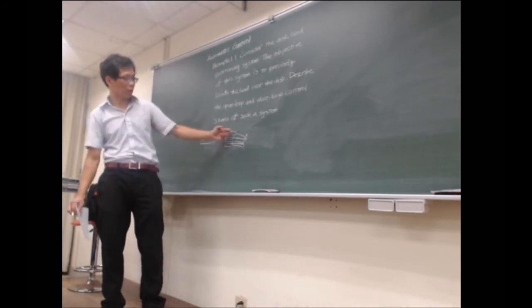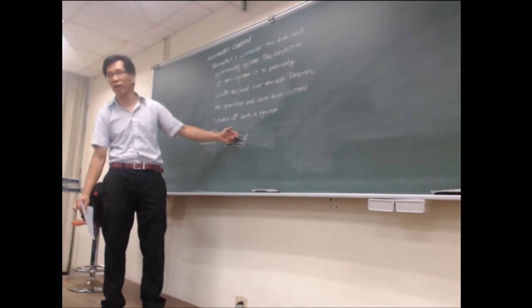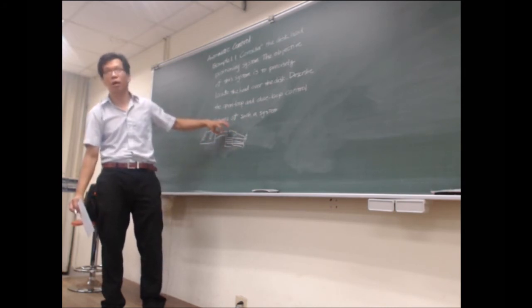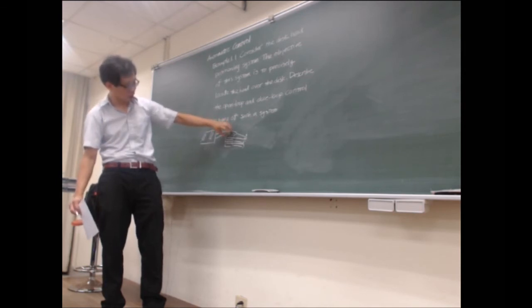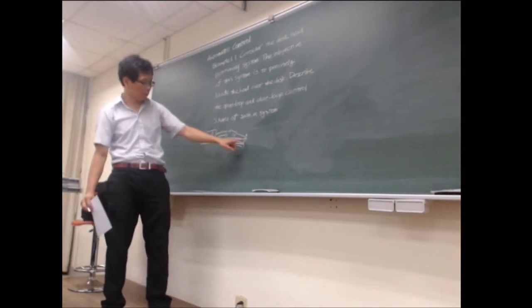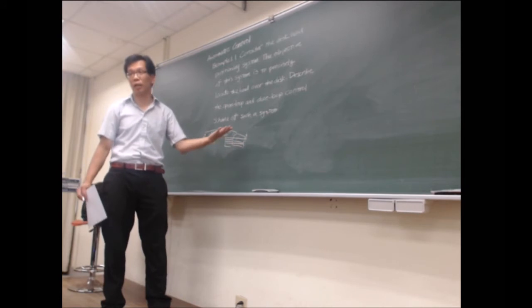One is a piezo material over here, so it will fine-tune the position of the reading head. And the other one over here is a voice coil, so you can actually rotate this one in a larger range. So combine those two things together, we can control the reading head anywhere we want to on the disk.